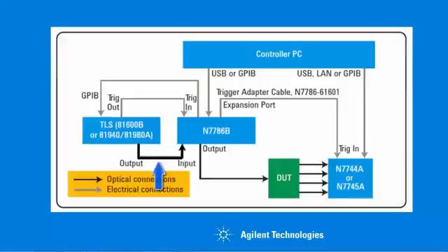We have a connection from the tunable laser output to the input of the polarization synthesizer, and then the output of the synthesizer either goes through the device or is connected directly to the multi-port power meter for reference measurement.